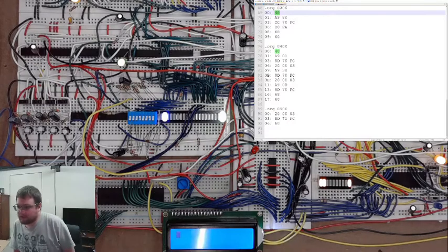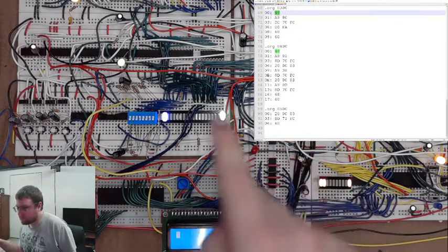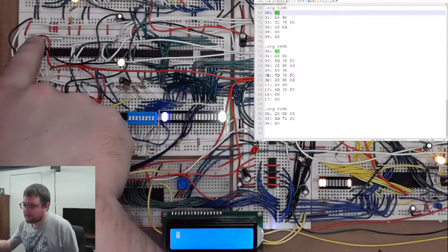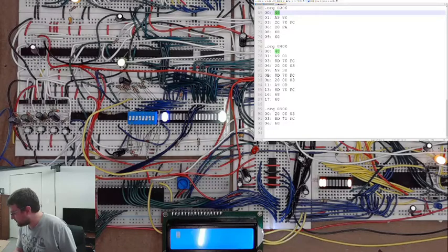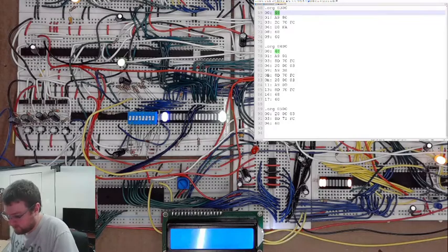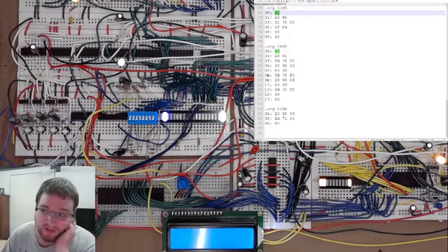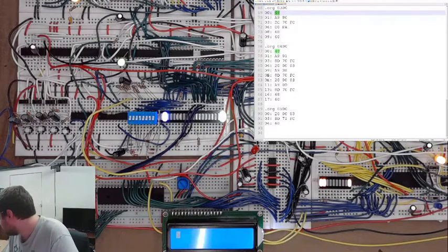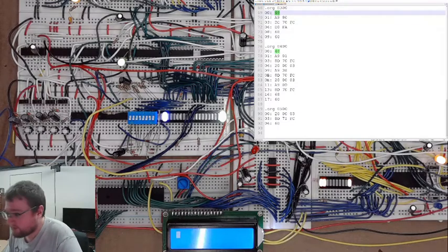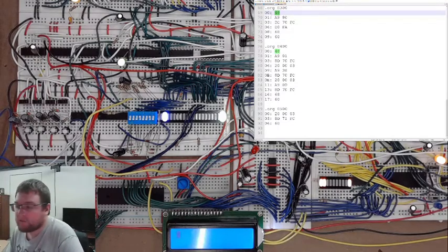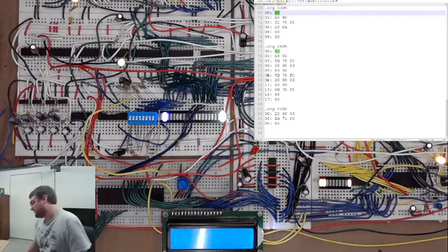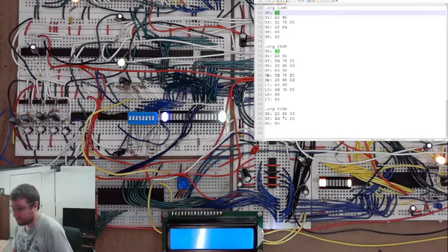And I'm beginning to think it's a problem of these, though, like, you can't see that one. I've got these capacitors running across some of the more important chips. So I'm beginning to think maybe I need to do that elsewhere to get things working better, just because I think it might be a power availability problem. It would be best if I could do it to every single chip. I don't think I can. If it ends up that I have to, I guess I'll figure it out.